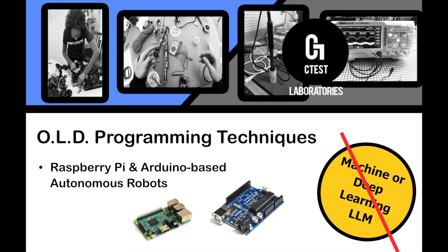Just a note there also, we tend to have maybe an Arduino dedicated to 1 or 2, sometimes 3 sensors. We'll have another Arduino dedicated to servos. We might have another Arduino dedicated to motors, maybe another Arduino dedicated to just a camera subsystem. And so just to let you know, we don't have an architecture where everything is done with a single Arduino or everything is done with a single Raspberry Pi.